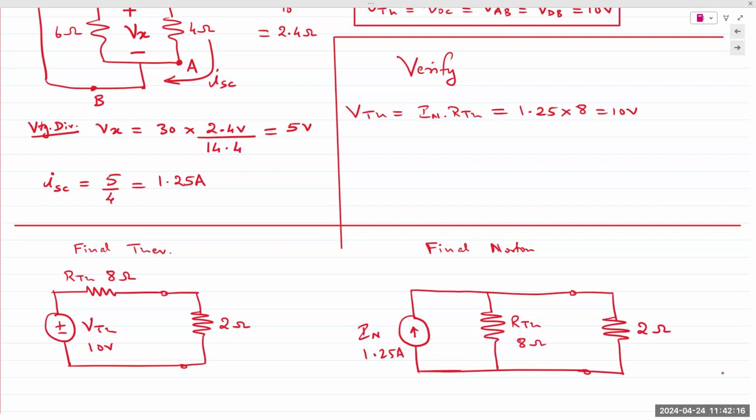If you connect a resistor in parallel with a voltage source, what is the voltage across that resistor? It remains the same because it is in parallel. So if you need to show that some of the voltage is being consumed internally by the circuit, for a voltage source, you always state it in series. For a current source, you always state it's in parallel.